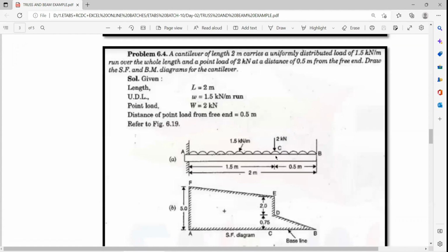And this point load you have to apply over the frame, over the beam. So tell me, is it needed to break the beam here, or can I take the continuous beam? No need to break the beam. Exactly, very good. So it is not needed to break it. We can take a single element. It is a single beam. Okay, so why are you going to break it?